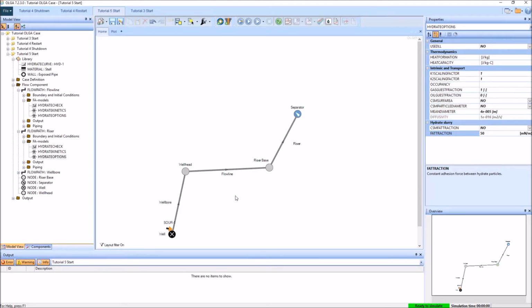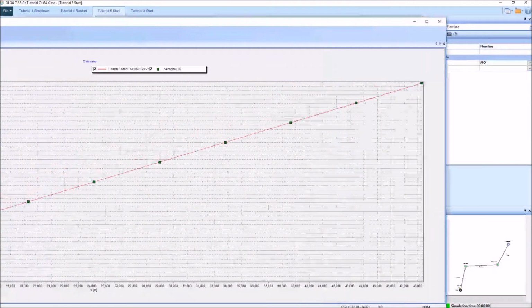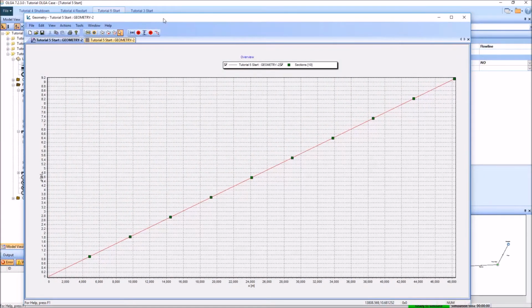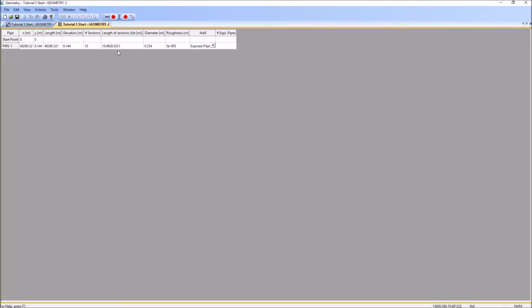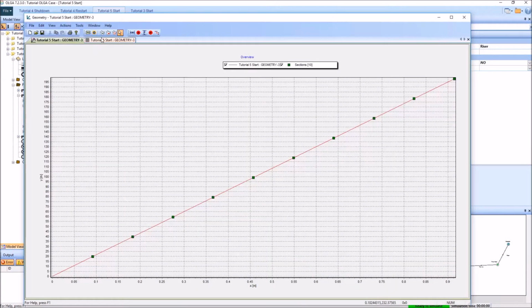Okay, now one final thing that we're going to do is to just change the resolution of our simulation slightly. So when we were doing our simple calculations and we just wanted to know approximately how things were moving, it was okay to use a relatively coarse simulation. You can see here we have 5 kilometer nodes or control volumes. What we're going to do is to increase the resolution of our simulation, and we're now going to have 1 kilometer nodes. So we can close this and say okay,